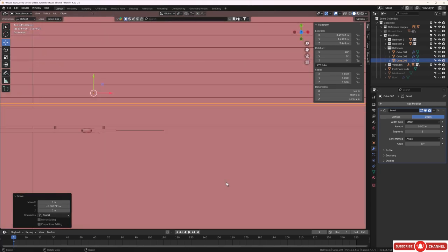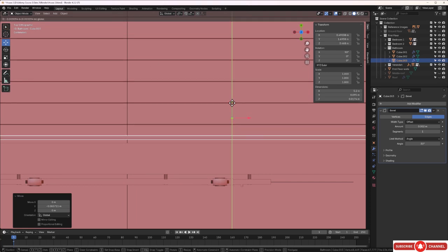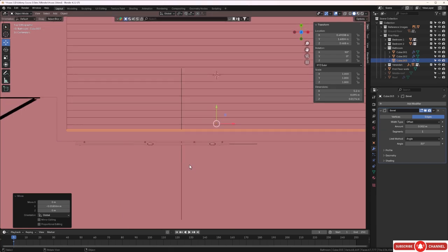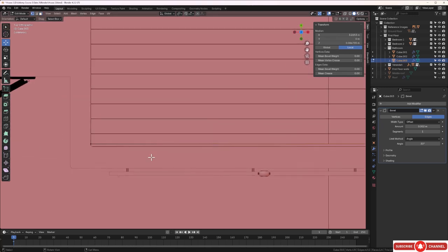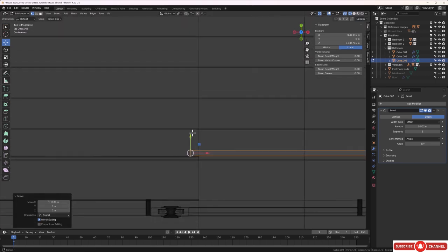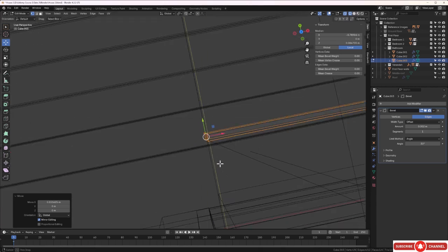Let's press 7 so we can see this from above. Whoops. And let's go ahead and take that over now to the wall. Like this. That's what I want. Let's tap into edit mode with it. And let's press 1 so we can select vertices. And let's go into wireframe mode. Grab these vertices here and bring these back until they're level with the door opening. Maybe a tiny bit forward, but not much. Maybe just that much forward of the door opening.